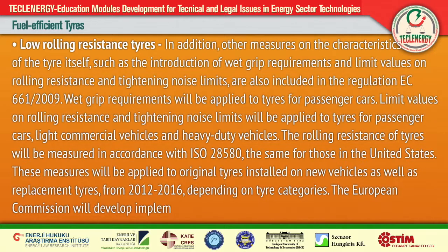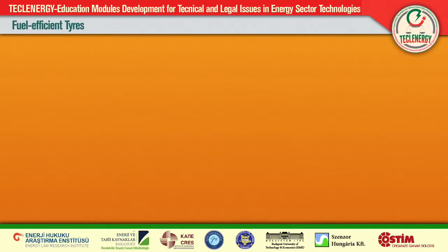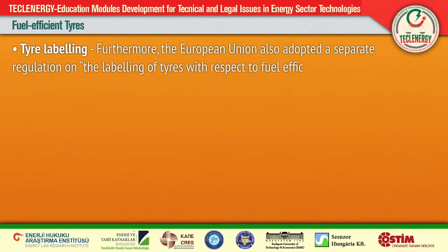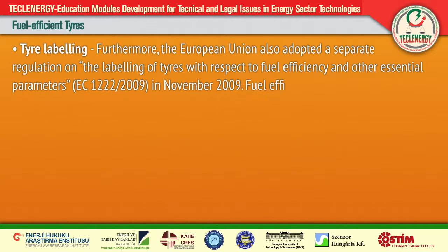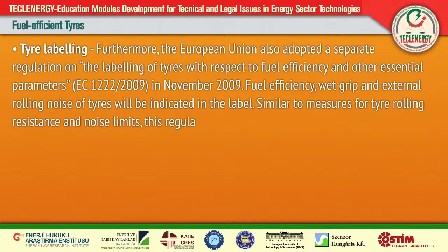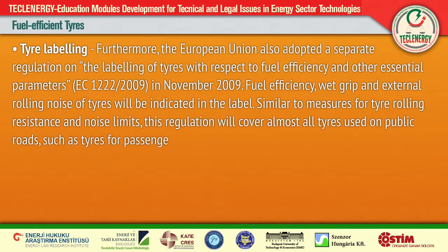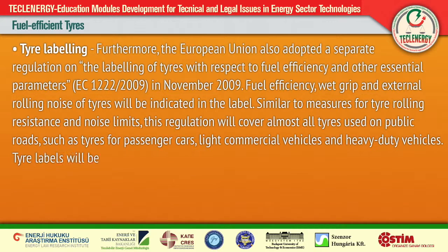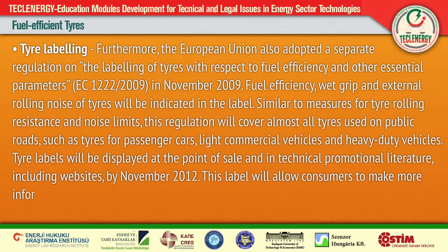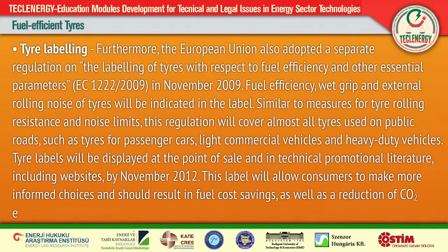Concerning the technical rolling resistance of tires, tires with low rolling resistance are already available on the market. In the European Union, some modern tires have a rolling resistance up to 30% lower than the best tires produced in the early 1980s, while the worst tires on the market have twice the rolling resistance of the best. The three key issues are presented: TPMS, Tire Pressure Monitoring Systems; LRRT, Low Rolling Resistance Tires; and TL, Tire Labeling.